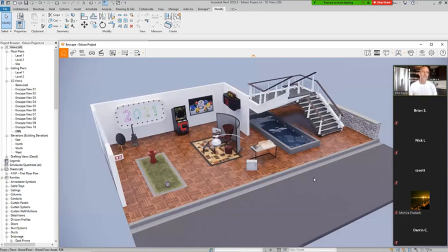And a big part of that is getting ready for post-production. There's very few times where you just create an animation out of Enscape and send it directly to the customer. I like using Camtasia for post-production, but effectively you want to get that animation started and set up as quickly as possible, even if you render it, because you can render it and then begin to set up what you need in post-production very quickly. And then when you come back and get everything verified, you can re-export the animation at a very high quality and then just swap that out in the post-production process.